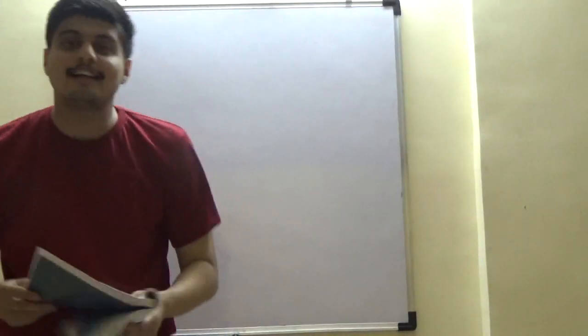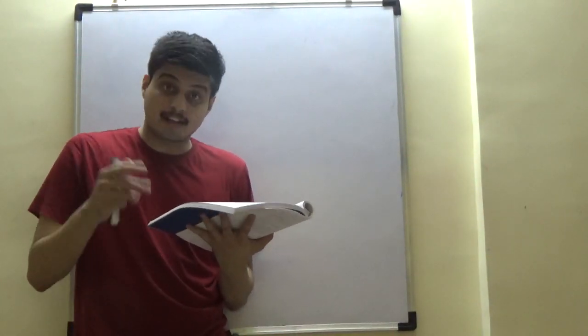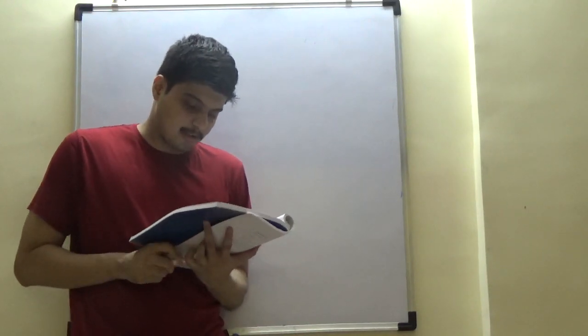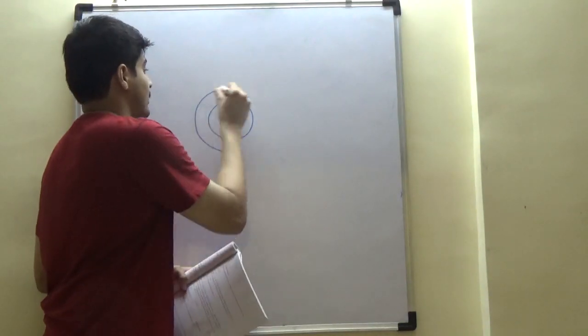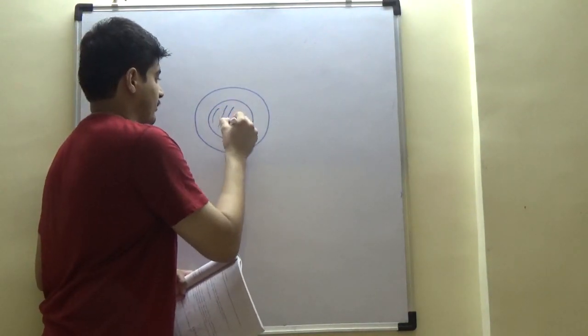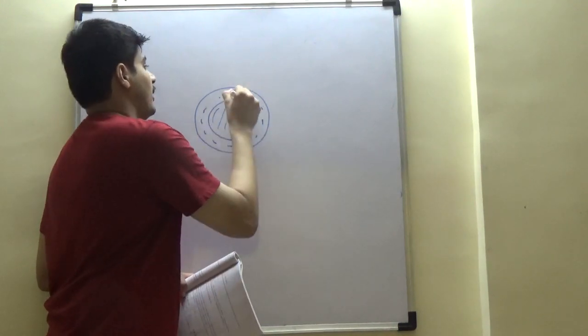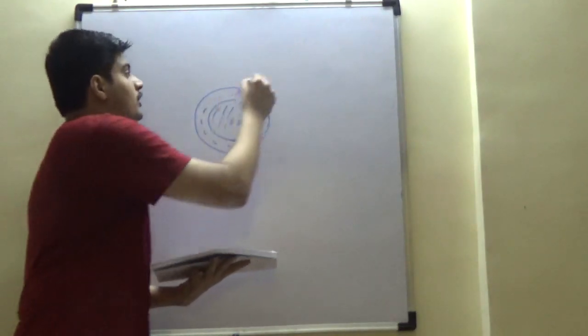Now after having these slightly heavy mathematical problems, let us look at a few qualitative problems as well. A composite circular shaft, this is GATE 2013 by the way. A composite circular shaft is composed of a steel core surrounded by an aluminium annulus. So it is this composite bar. So this is SS and this is aluminium. Okay, that is given. Perfectly bonded to each other.